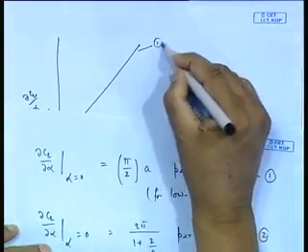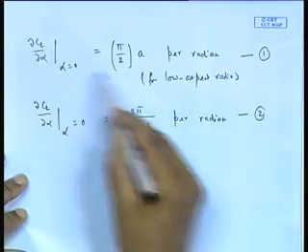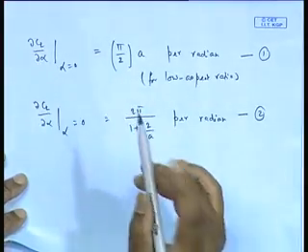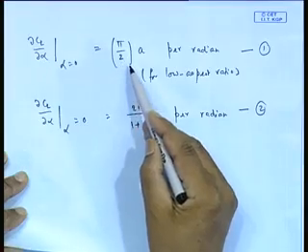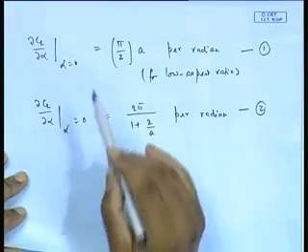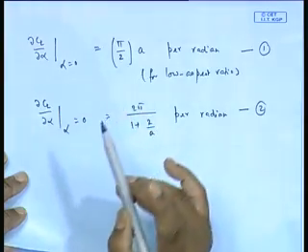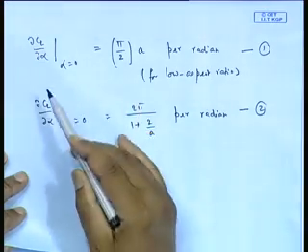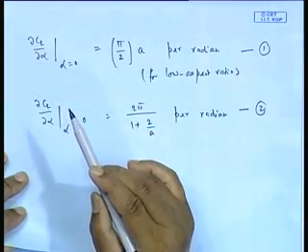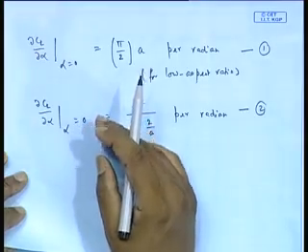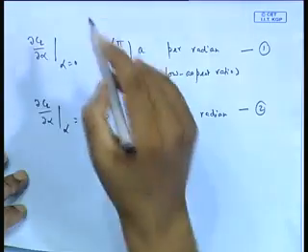formula 1. Remember, dCl by d alpha here is the first formula provided by Jones. Somebody has given this estimate. It says dCl by d alpha is simply proportional to A. See, this is why I am saying there is an important point. This tells me that if you have a low aspect ratio, then you do not get much lift. So, therefore, you do not want to make the aspect ratio low. That is why I was trying to tell you about this 1.2, 1.3 aspect ratio. Remember, I will come back to this aspect ratio part.